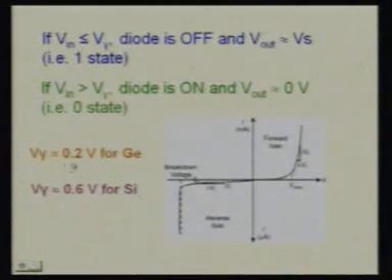So if voltage is greater than 0.3 volt, it gets into saturation. So we have a huge current, and the voltage drop will be only 0.2 or 0.3 volt if the semiconductor or PN junction is made of germanium crystal. And if it is made of silicon, then the voltage drop across that PN junction will be 0.6 or 0.7 volt. So by our definition for positive DC level logic circuit, it is a low state. So now we will keep these things in mind for our further discussion.